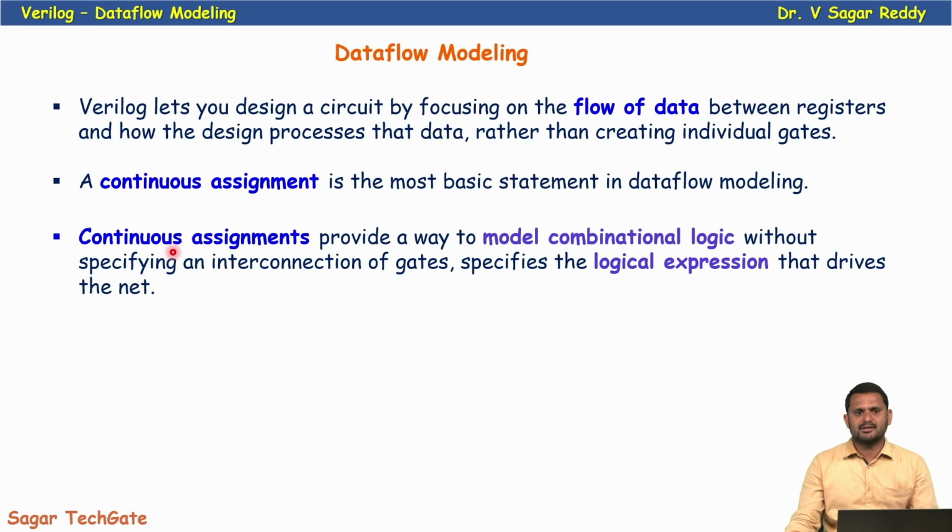The continuous assignment statement provides a way to model combinational logic without specifying an interconnection of gates. We specify the logical expressions that drive the net. So in data flow modeling, we use continuous assignments and logical expressions to describe combinational circuits. By using these, we define a relationship between input and output.